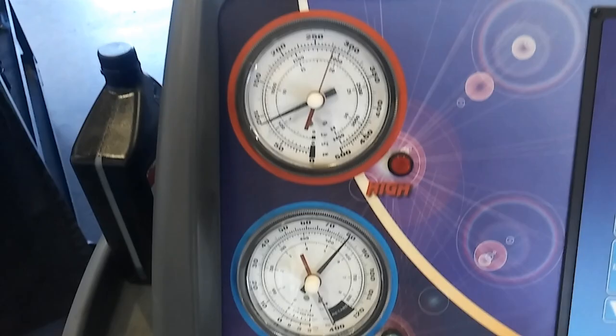Now, whether you're using your AC machine or a set of gauges, at a minimum you're going to hook up to this system anytime you're changing a component. The reason is to look for pressure. Even though we verified that this system has a leak, it still has about 85 psi of pressure in it. So there's still refrigerant in there, but probably not the appropriate amount. You're going to have to recover it in this case, so you would need an AC machine.